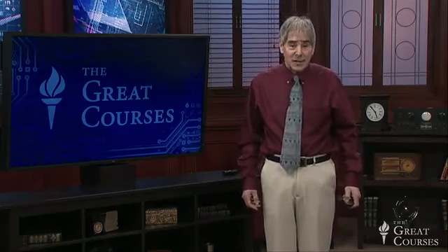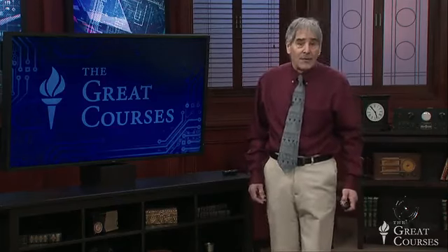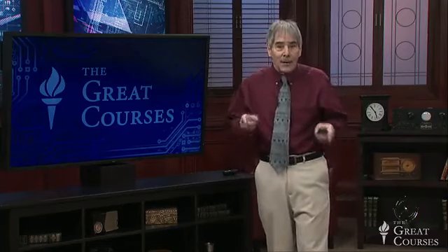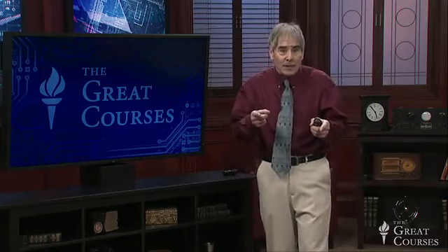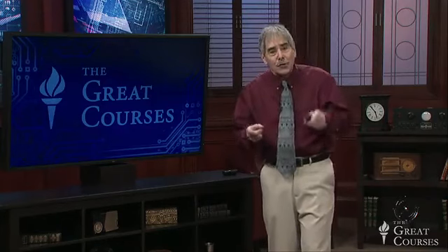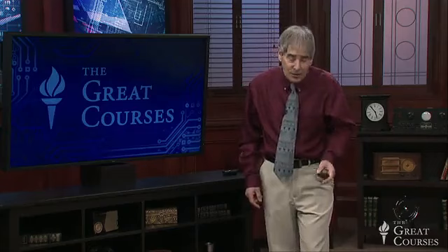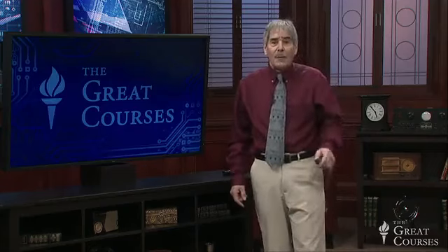So this is a summing amplifier, and a very useful circuit, and it works because we have this virtual ground at the minus input of the op amp, which means that the two currents can flow independently without either one knowing what the other one is doing. And before we move on and actually look at one of these amplifiers in the flesh, as it were, let's look at two other possibilities.